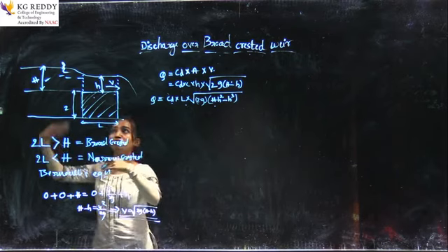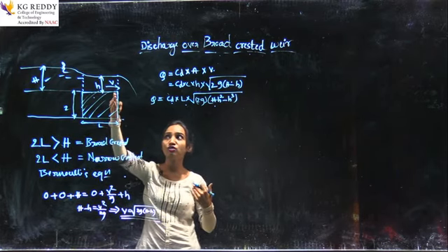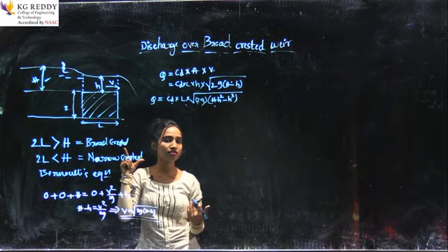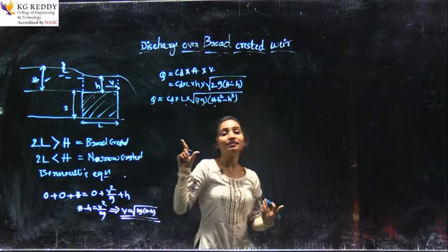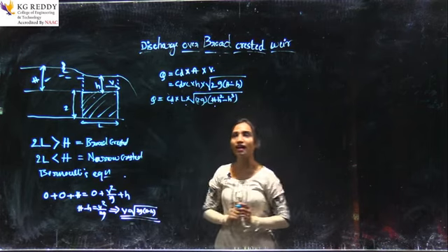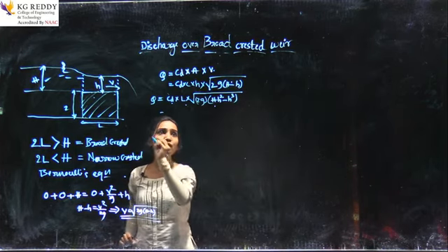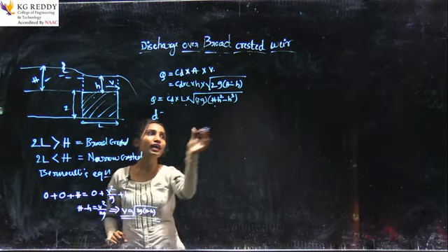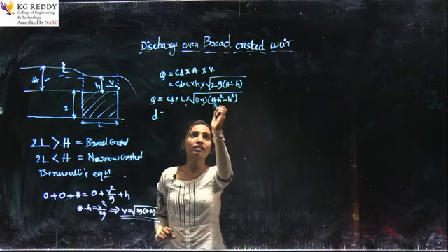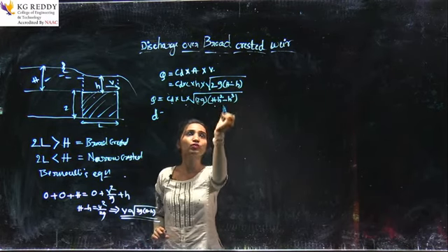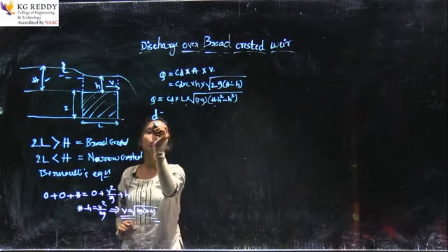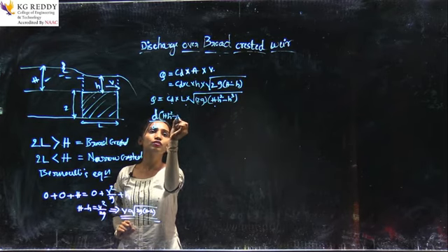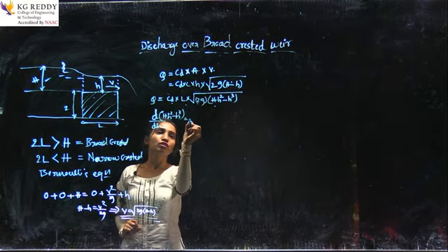If you see here, when water flows over the notch, whether it depends upon the length or else the height, discharge. If you are fine, the answer is h. Yes, you are right, it is the h. So, I am taking this as the maximum discharge we can achieve. If the h is maximum, we can get maximum discharge. So, d by dh of what term am I taking? H into h square minus h cube is equal to 0.